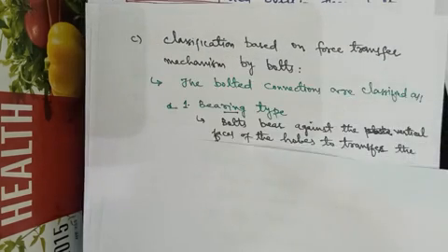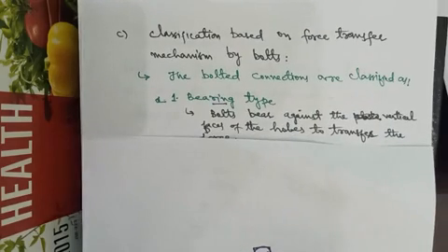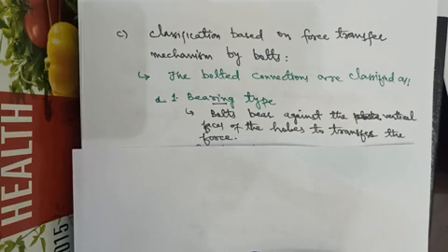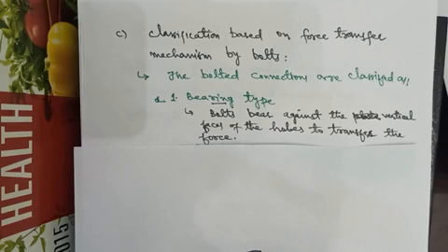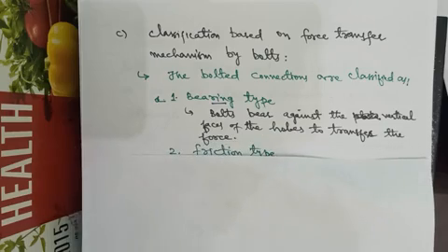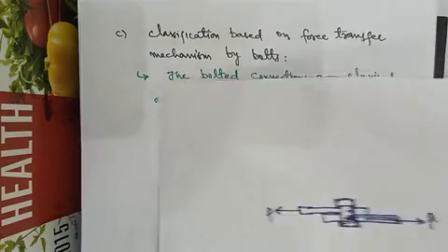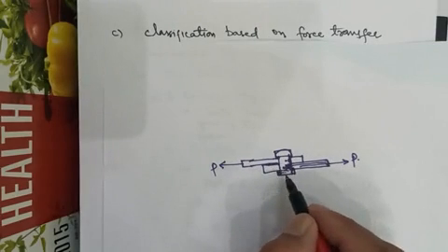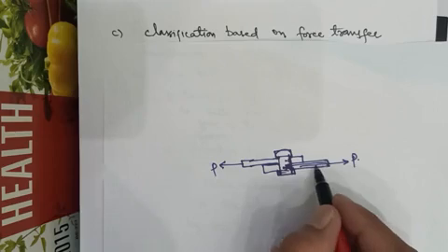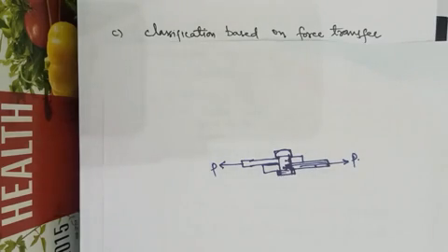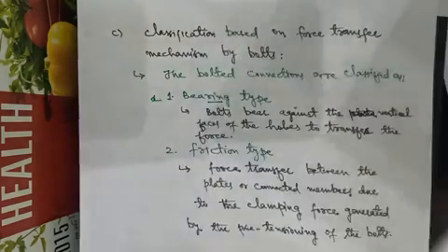So when the force is applied to this member, this force gets transferred to the bolt and the bolt pushes against the vertical face of this hole. This is called bolts bearing against the vertical face of the hole to transfer force, and by way of this mechanism the force gets transferred from the plate to the bolt.